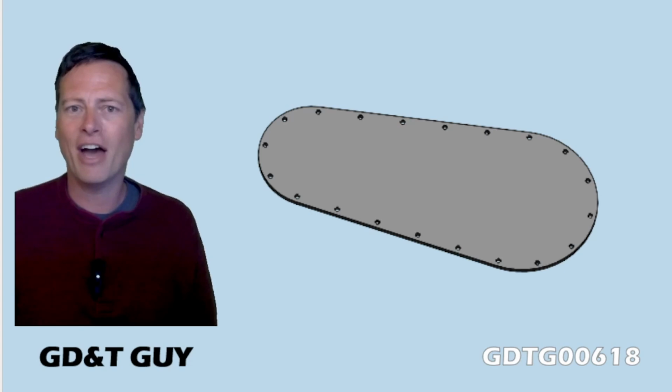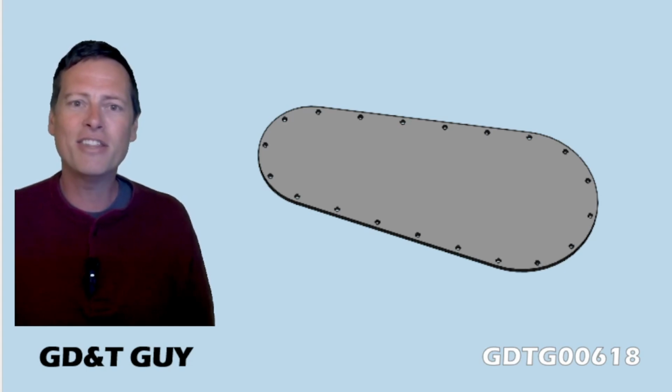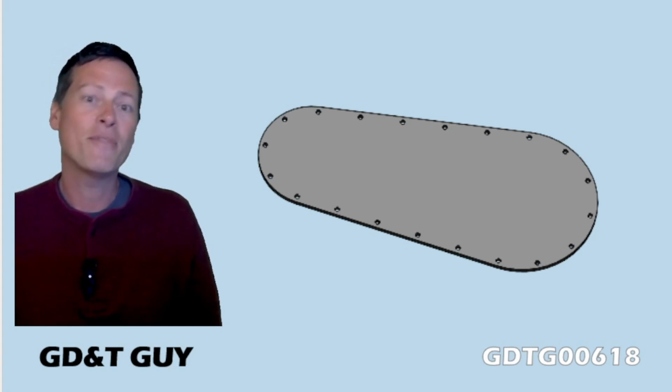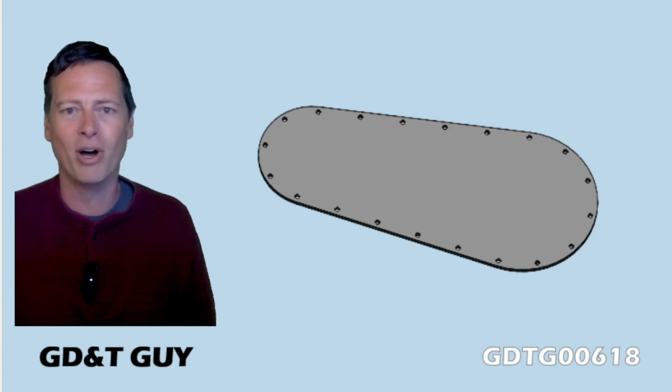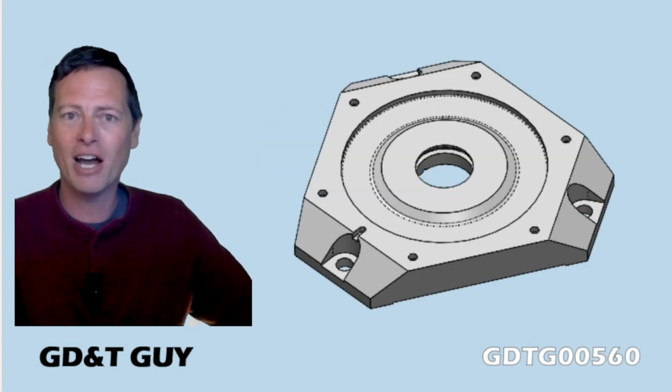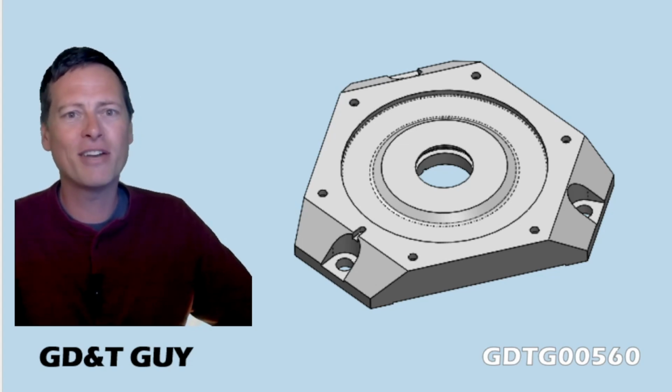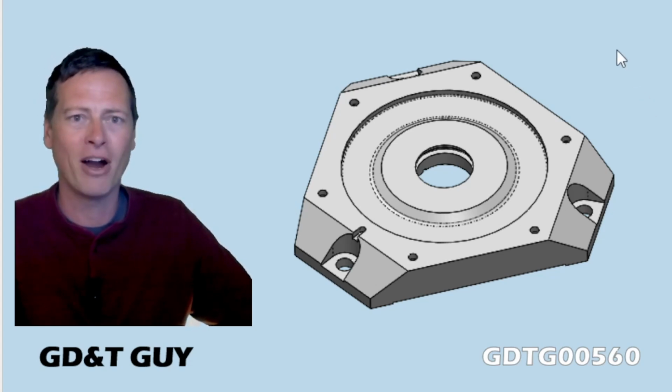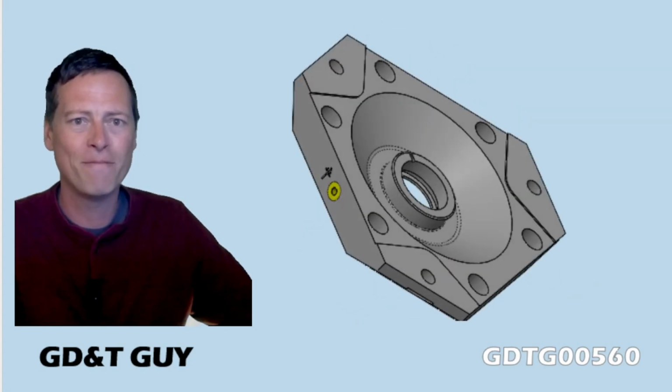I'm going to tell you that the outer profile is not particularly conducive to being a datum feature, in most cases, and neither are the screw clearance holes. That topic goes all the way back to episode 1, and I plan to dig into that some more. All right, and it's not just the cover plates. I've come to see that it really doesn't matter how complex a part is for this stuff to apply.